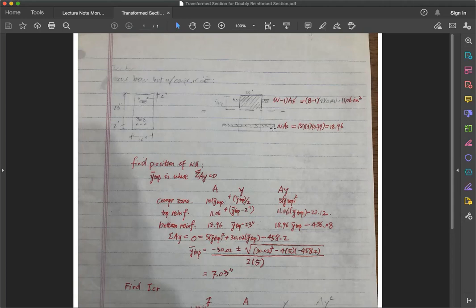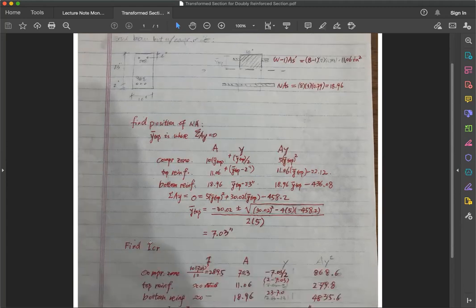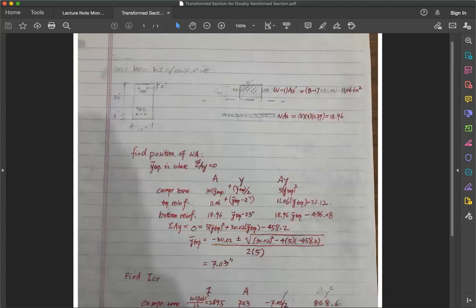So you have to actually get the compressive reinforcement considered. Since you have compressive reinforcement at the top, you do that assuming you have an uncracked section for the compressive reinforcement part. By the way, this is for I cracked, I_cr, not I_gt. When you have the compressive reinforcement, simply convert that into (n-1) A_s prime, that is the compressive reinforcement area. And then you have the bottom bar, which is A_s.